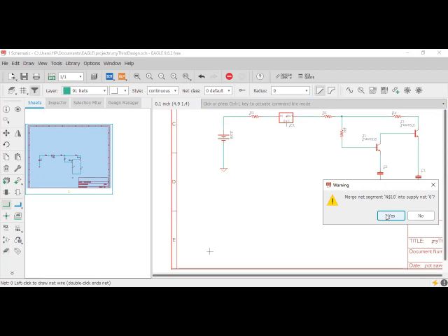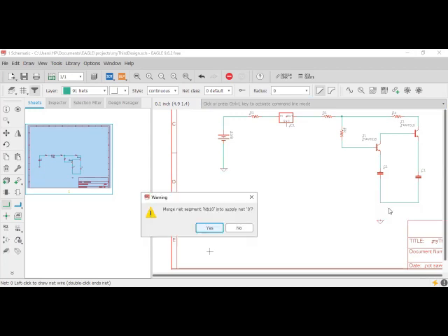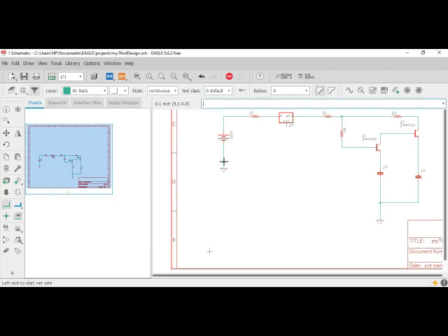Yes, we've merged. So we are merging this due to the fact that this has the same elements with the other one. This and this have the same elements, are the same components. So if I connect these to another component and I connect this to another component, a warning like this will show: am I trying to merge this and this together? So I said yes. We merge it, definitely this and these are the same. It's like you make a connection between them.